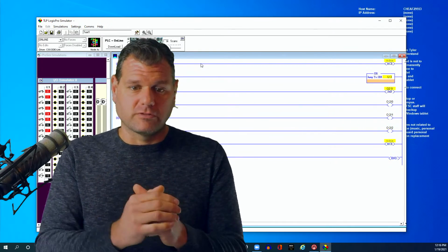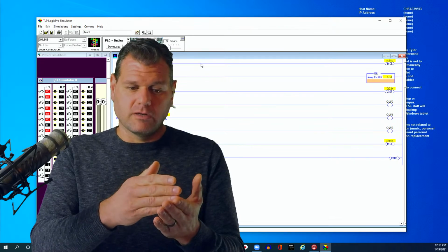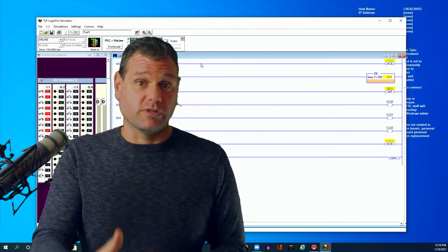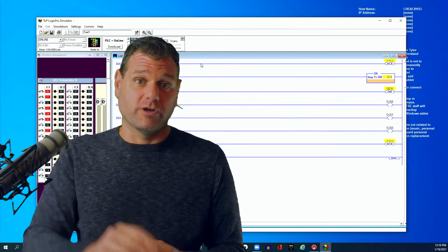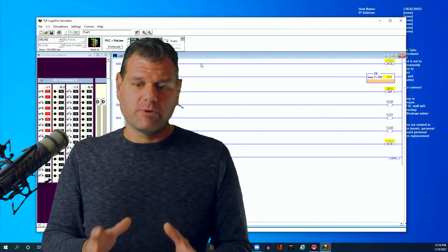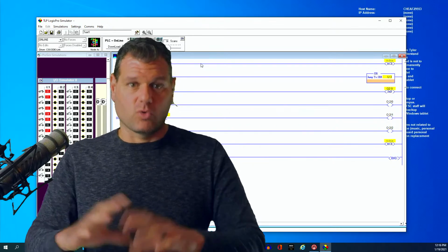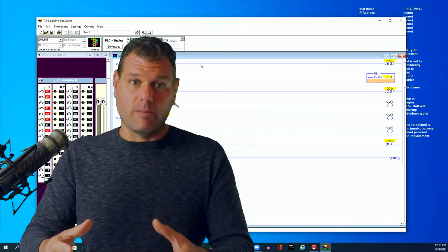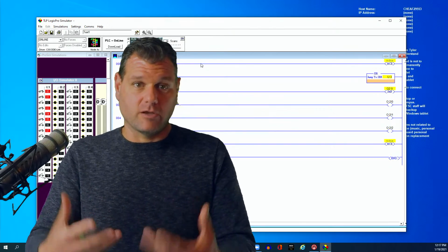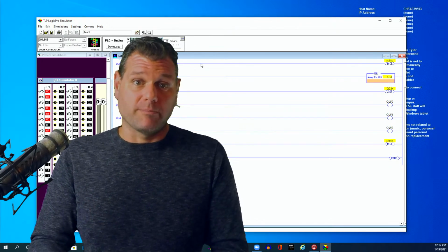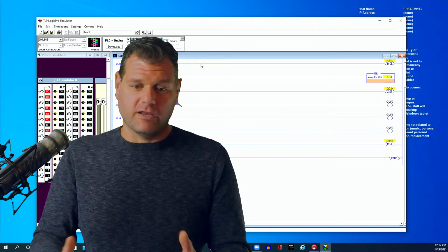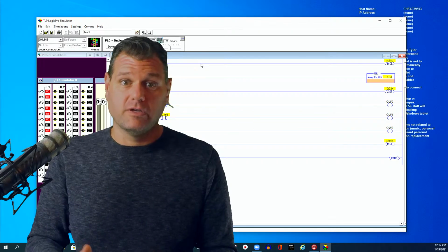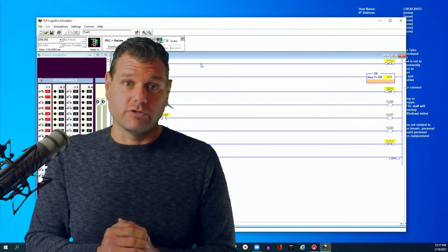There's another method I'll show you in a second, but you could do that and say, okay, I'm going to take it out of the code altogether so it doesn't rely on that, or you could force the output and say the output needs to stay on. Typically, when you force things, you're going to be around it. Like you're actually going to stay in that area and watch it, because if a sump pump, if the tank goes dry, you're going to burn your pump up, right? If it's a fan and something happens, there's nothing going to shut that system off by itself. So you physically got to go in there and actually do your stuff.